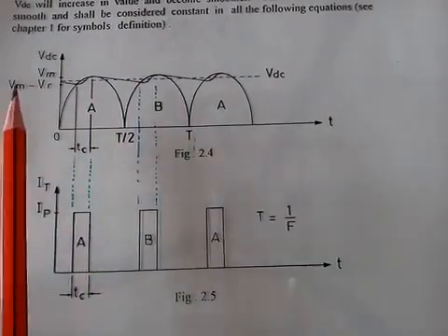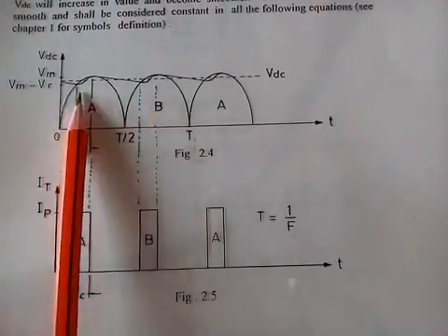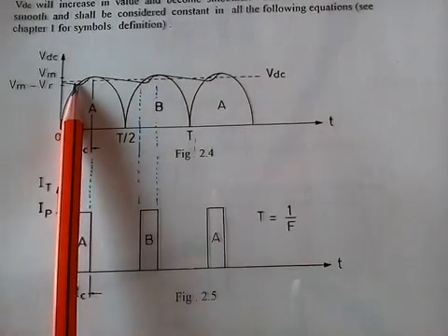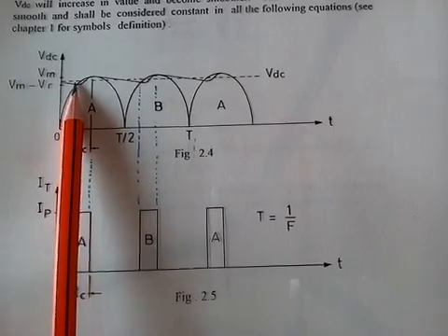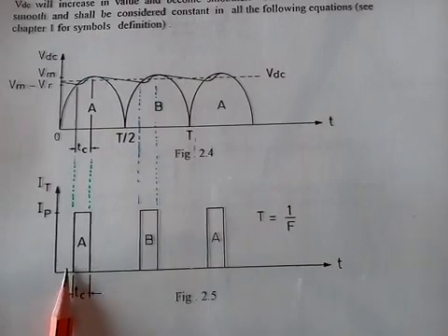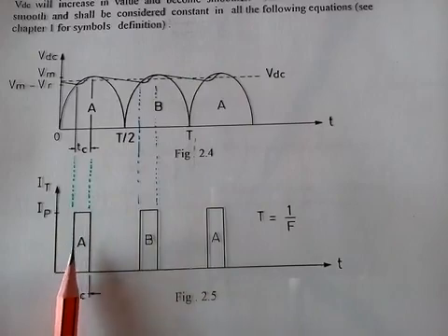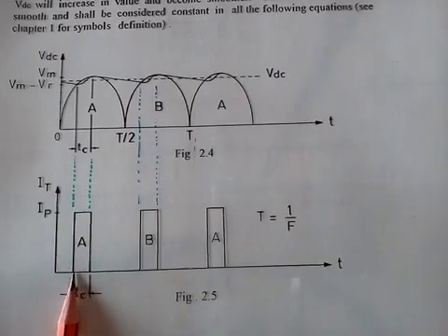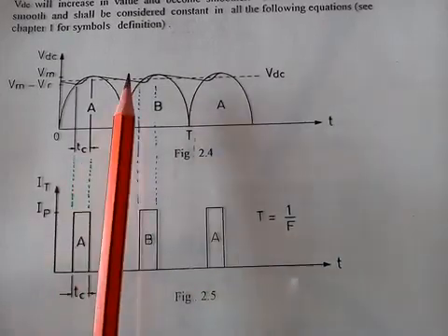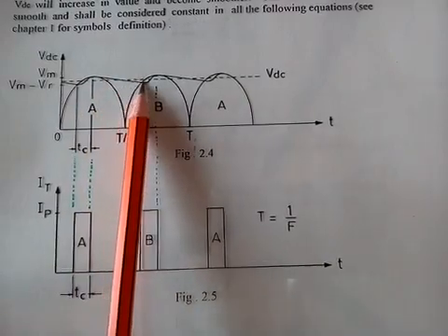Whenever the voltage across the transformer from winding A or winding B exceeds the value of the storage cap, the transformer starts charging the cap with high pulses like the one we see in here. Now the charge put in during this little time must be enough for the cap to supply the load for the rest of the half cycle.